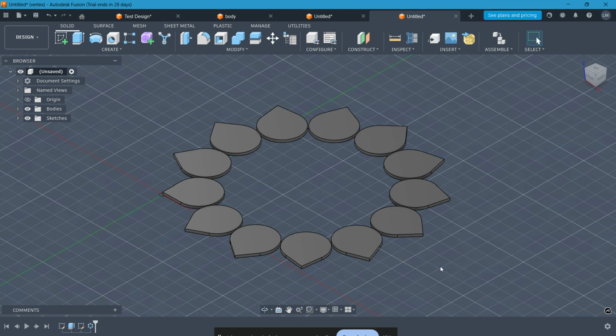Alright, let's jump right into it. First, you will need to have a project or a part open within the Fusion 360 interface. Once your model is on the screen, look at the very bottom center of the workspace. You will see a small navigation bar with several icons. We are looking for the Display Settings icon, which looks like a small computer monitor. Go ahead and click that icon to open up a secondary menu full of visualization options.